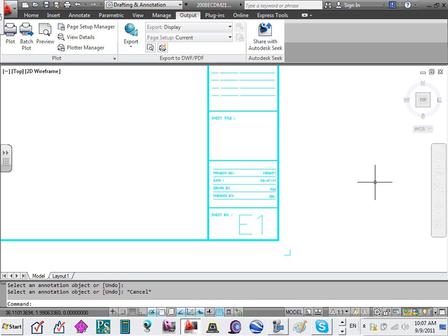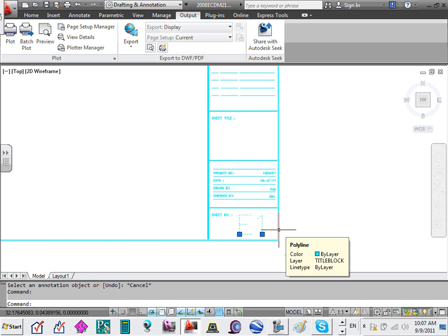So what I'm going to do then, instead of having E1 here, this E1 should not be here. So I'm going to go there and delete it. Delete the E1. E1, E2, E3, E4, 5, 6 through 12, we don't write them here. Why? Because if you extract E1, guess what's going to happen to all your sheets? You're going to show what? E1, E1, E1, E1. So we don't do that. We do it on the sheets themselves.